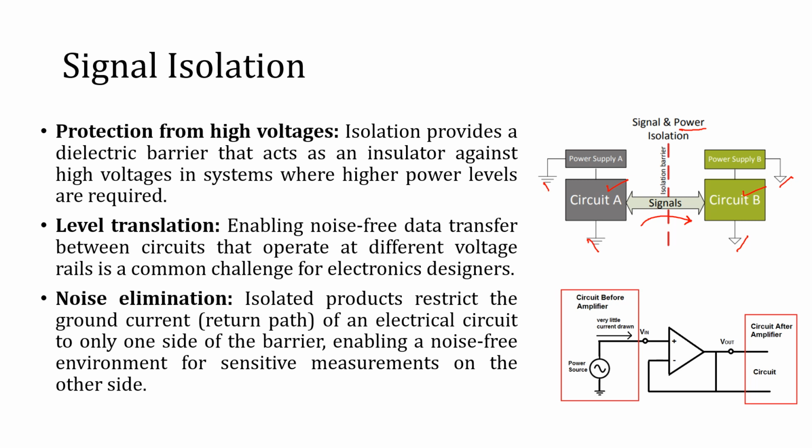So different symbols have been used for the ground to explain that there is power isolation also, in addition to signal isolation. That is, the circuits are working on different power supplies, so there is no direct connection between their powers also.